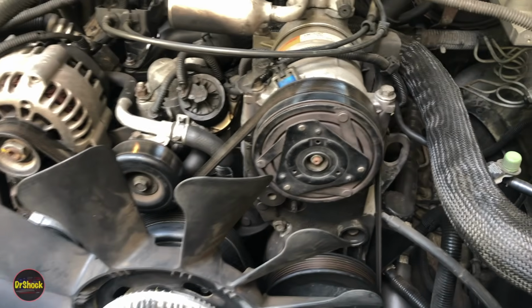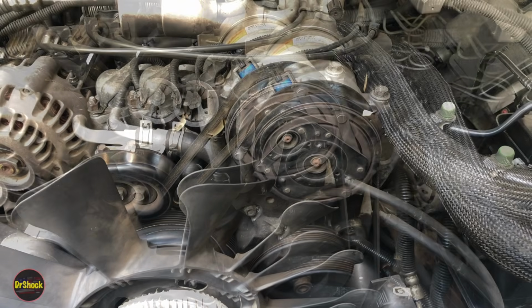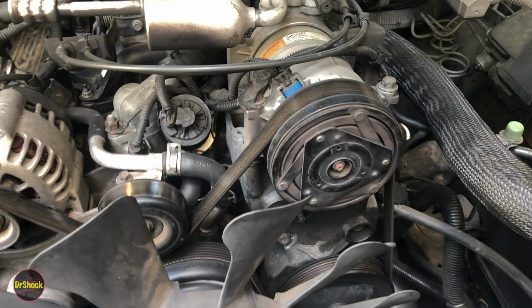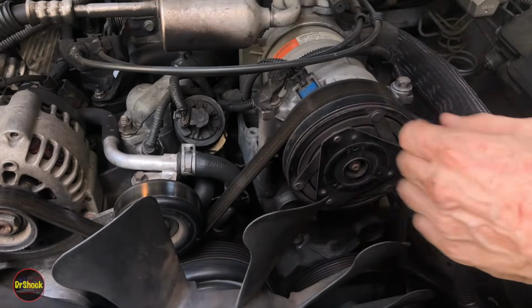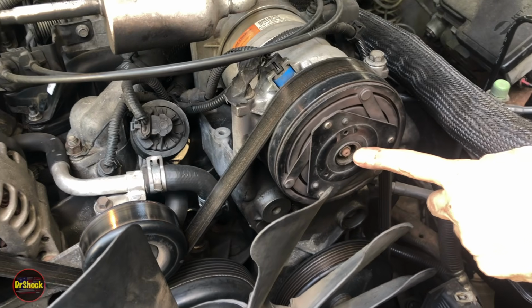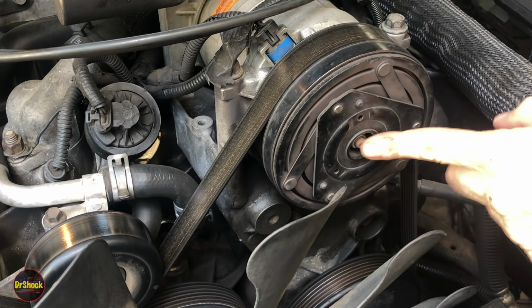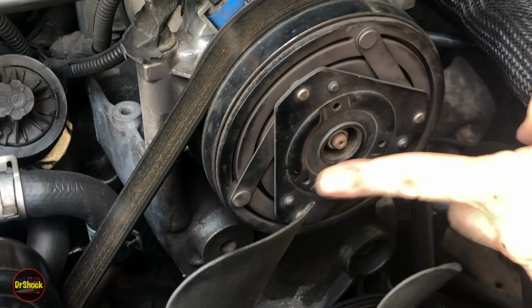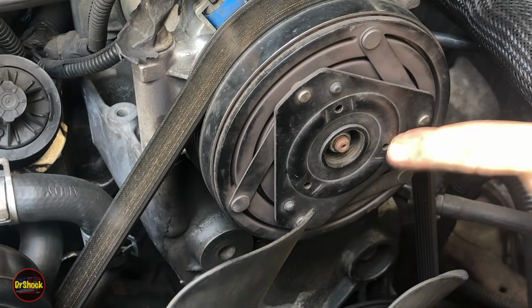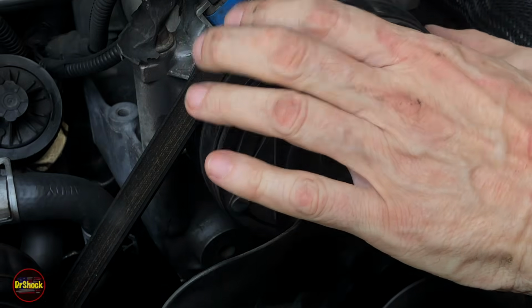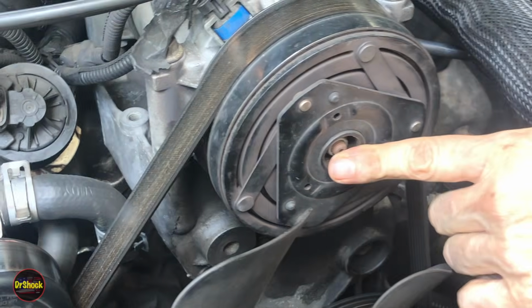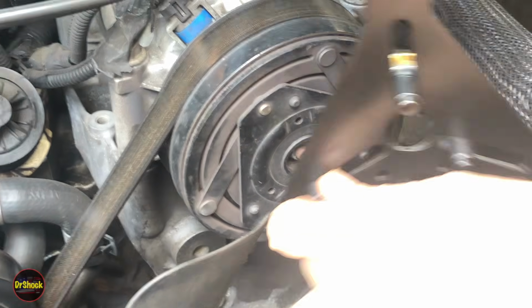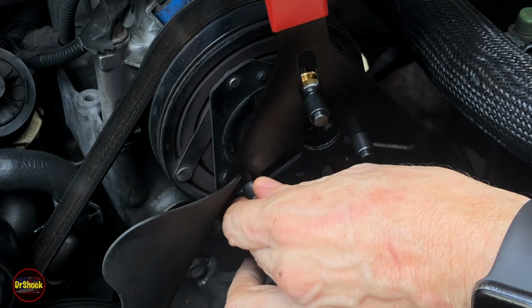All right, so let me get the special tools and we'll go ahead and adjust this air gap. Like we were talking about in the previous clip, we want to close this air gap. Before we can do that, we got to get this 13 millimeter retaining nut off the compressor shaft. You see these 3 depressions here are for a holding tool. Sometimes the belt is enough for this particular step, but I'll go ahead and show you this tool in case it's not. We'll just use it anyway.